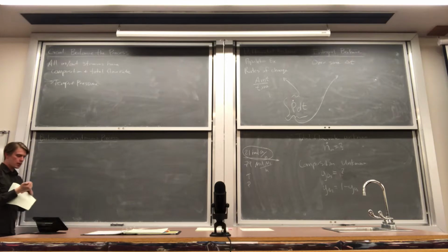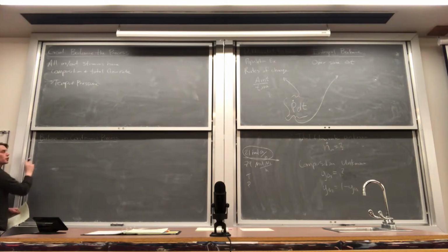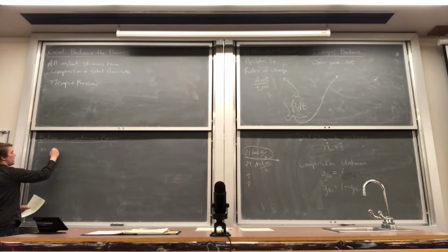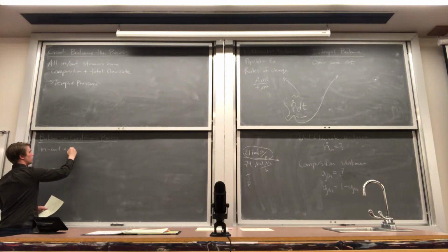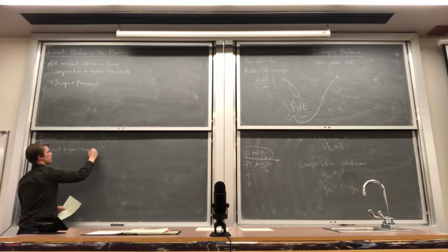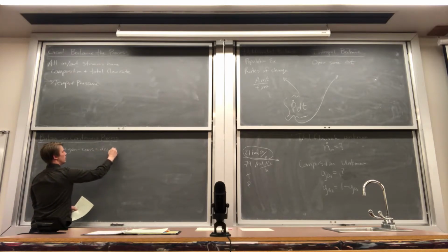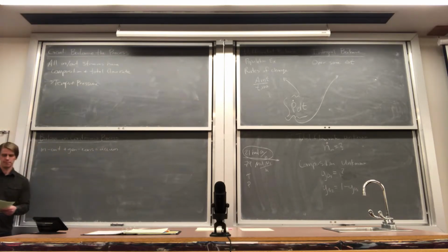Okay, so on a continuous process, let's write out our general balance equation. In minus out plus generation minus consumption is equal to accumulation. Let's simplify it. We have a continuous process. What term goes to zero?